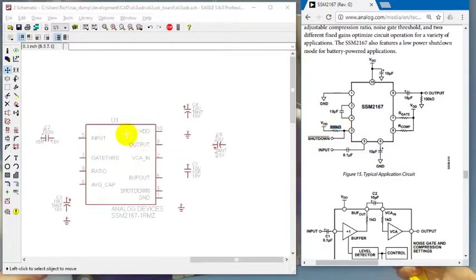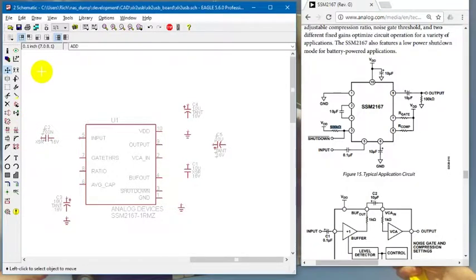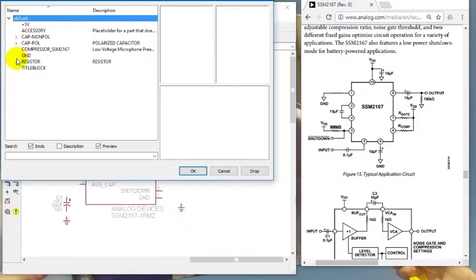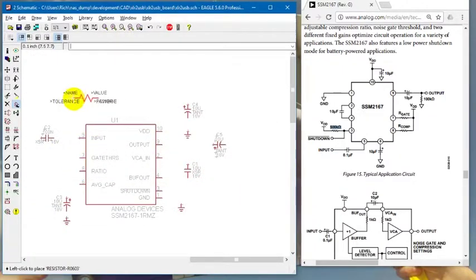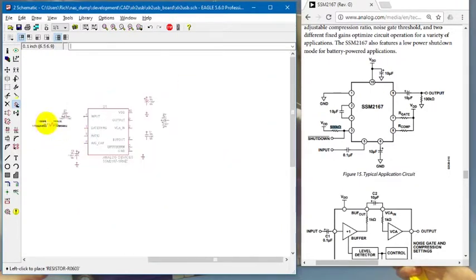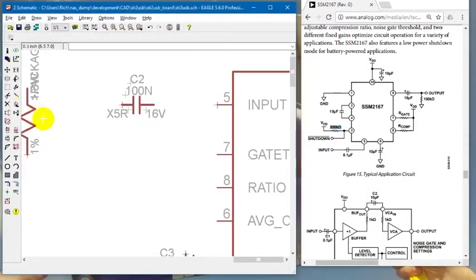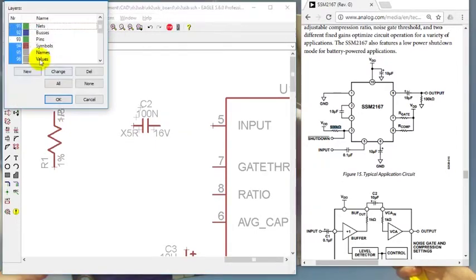Pin 3, the shutdown pin, has a resistor on it, which looks like a pull-up resistor to our power supply. So that's going to be a vertically oriented resistor. So add, oops, wrong program. Add a resistor. And I'm going to use these 0603s because I like them so much. Now this is a judgment call as to how you want to make it. I generally make pull-up resistors point up and down like this. And I'm already thinking that I may not like the exact way. Oh, that's right. I had 2 layers turned on. I don't want the power layer.